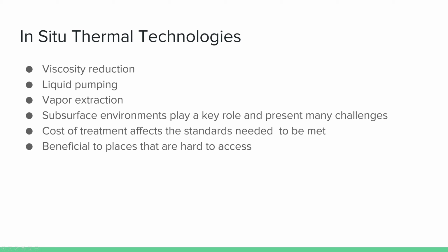Each of these methods are applied in situ, meaning without excavating the contaminated zone. Thus, they can be used in hard-to-access locations such as between buildings, beneath buildings, in deep zones, and at places where there is established infrastructure. They are low-impact methods relative to excavation, making them well-suited for use in industrial, commercial, and residential locations, and where there are mixed uses. They are also relatively fast, meaning that the source area can be treated and removed in well less than a year if required.